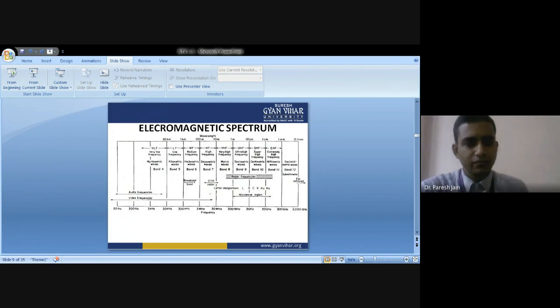So these are the specifically assigned bands used by the International Telecommunication Union for radar. Understand? That is acceptable by the ITU for radar. So these specific bands are only for radar, and this is governed by or accepted by international bodies. So you learn these frequency bands and understand them very well.